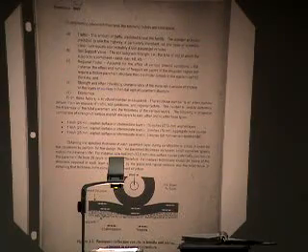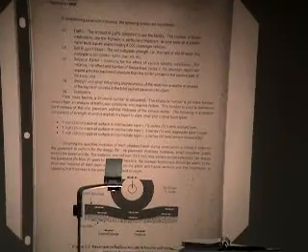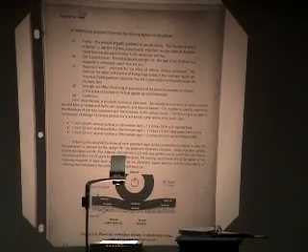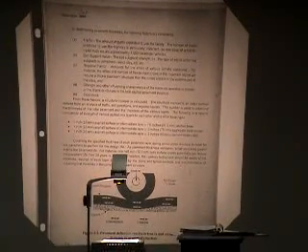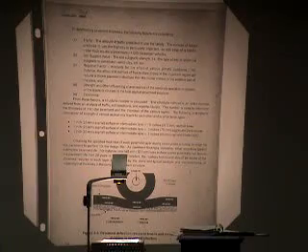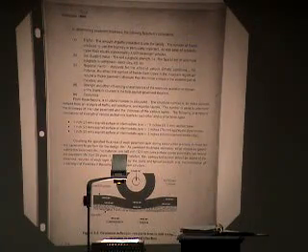The strength of the different layers themselves, as I said earlier: the surface layers have to actually be stronger on a per inch basis than the lower layers because that's where the load stresses are the greatest. That's where the tire load is being applied, and so that's where more rutting is likely to occur. So those layers have to be very stable such that they don't rut. And we'll talk about that in a little more detail here in a few minutes.